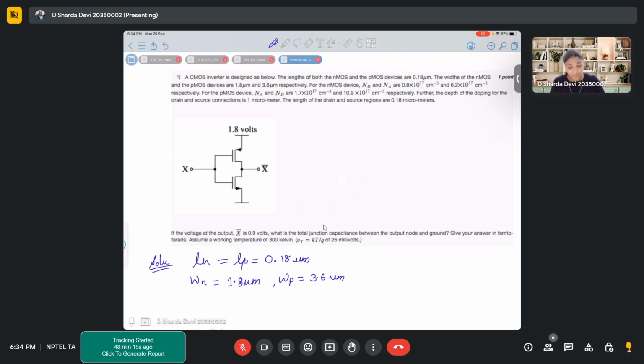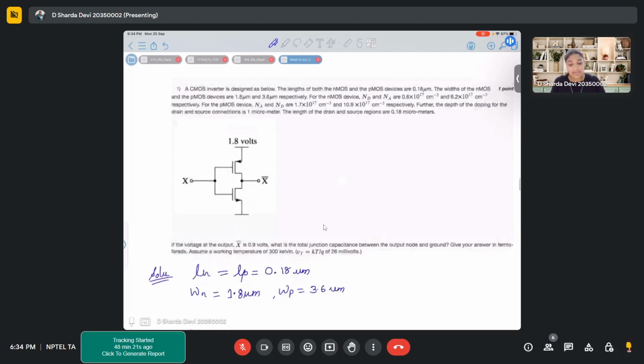Mobility of charge, due to mobility of charges. Yes. So when we are making a device, we always say that when there are two transistors in series, they have to carry the same current, correct? So for the same current, we know that the mobility of holes and electrons are different. We consider it on average to be double.